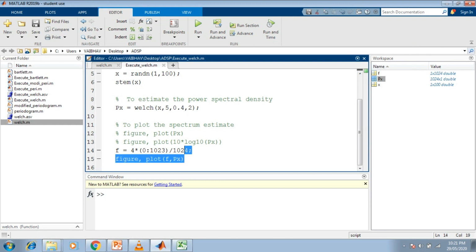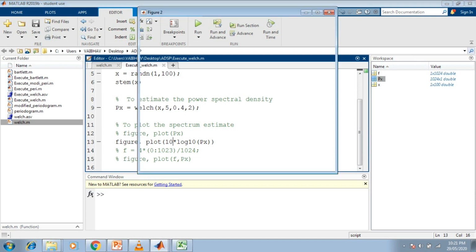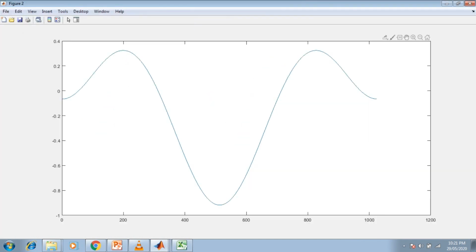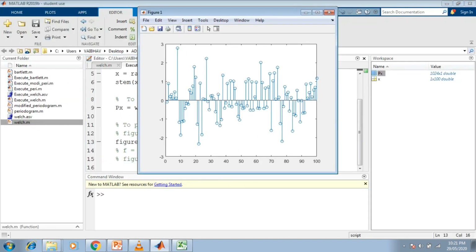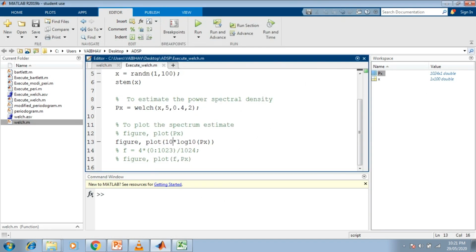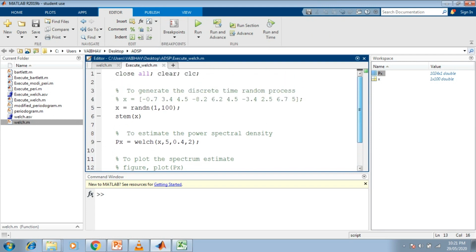Instead, if we make the use of only the plot of the spectral estimate having the decibel values plotted onto the vertical axis, we obtain such a plot. Here we have the decibel values of the magnitude plotted. At max, this graph extends to 0.54 value onto the positive side, whereas onto the negative side we have -1 decibel here. So this completes our simple MATLAB demonstration with respect to the Welch method of power spectrum estimation belonging to the non-parametric approach here.